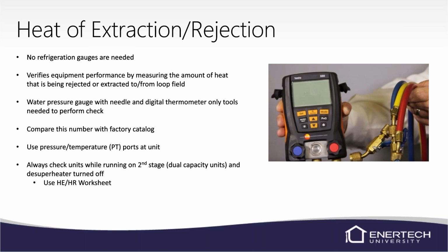It's not like airflow where you can just put your hand over a register or over the condenser fan motor and see if it's blowing air out. With water, it's in a pipe. In a perfect world, you shouldn't really be able to hear it, and you can't really feel flow either. So there's also no calculation that I can give you to establish flow. That's why we've got to have the manual. That's all engineered data, so we've got to use the manual for it.